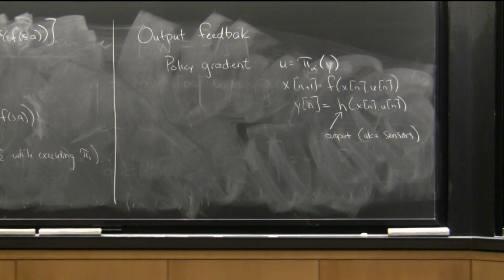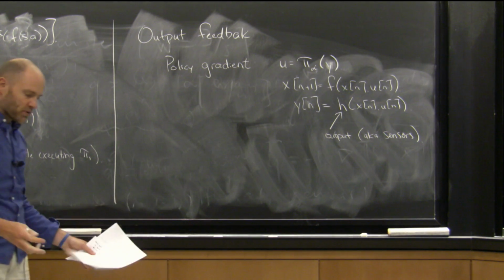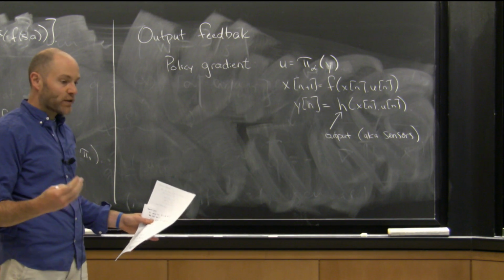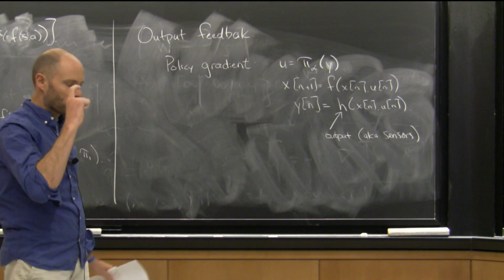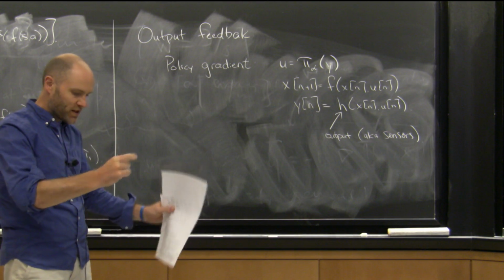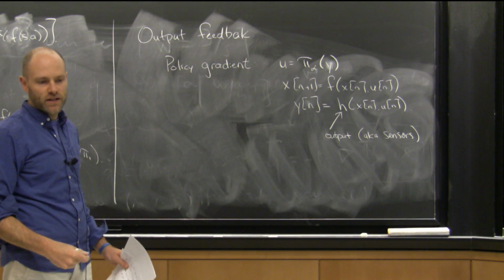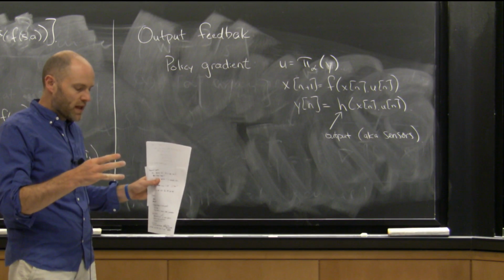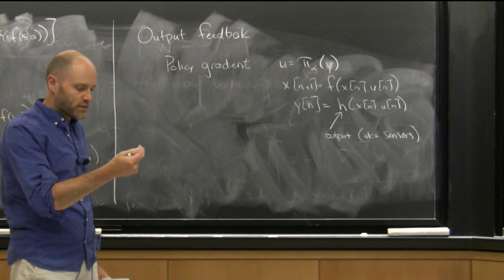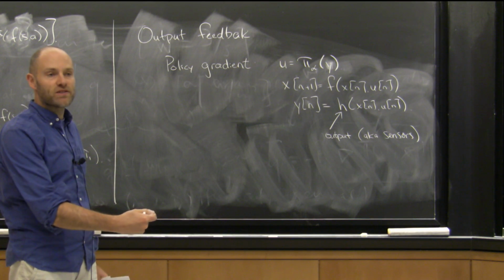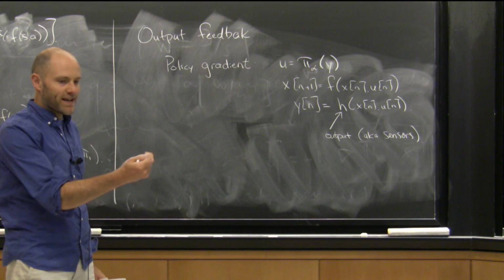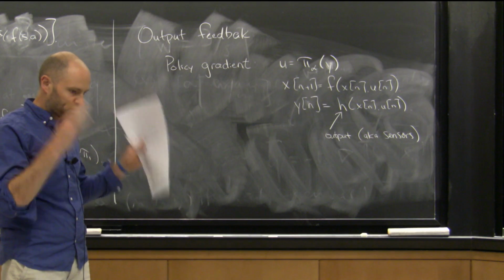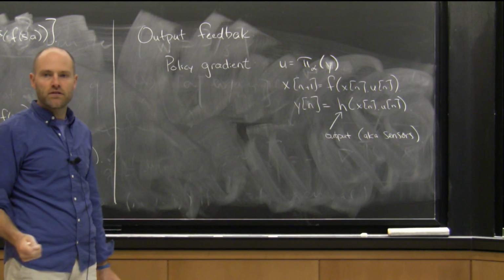So what does that mean? So I'm a robot trying to manipulate a towel. I can write down controllers which go from the image, my pixels, to my torques, if I would like. If I just want to take the image that the robot is currently seeing of the towel, I don't actually have to estimate the state of the towel. I don't even have to understand how big that state space is in order to write a controller that just maps from my current image to my torques.